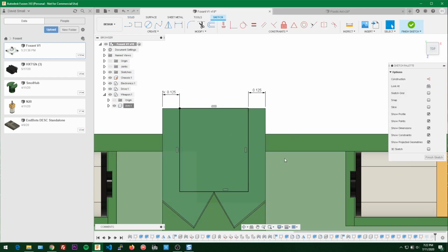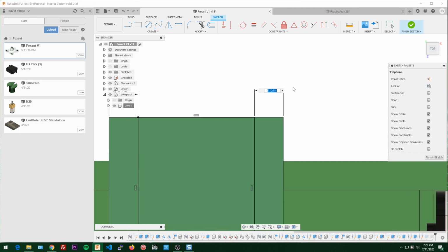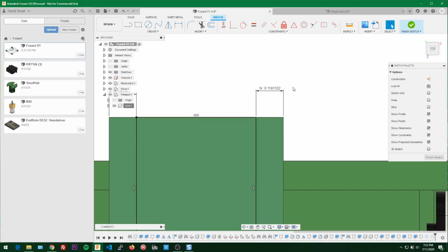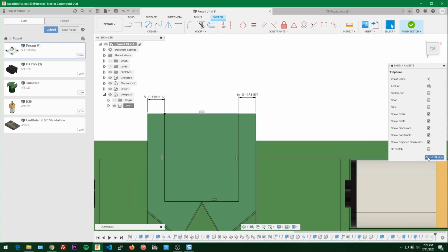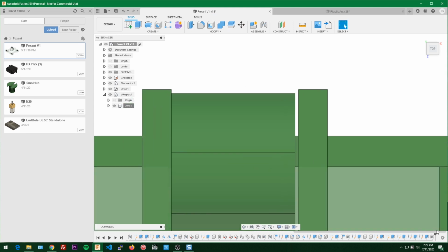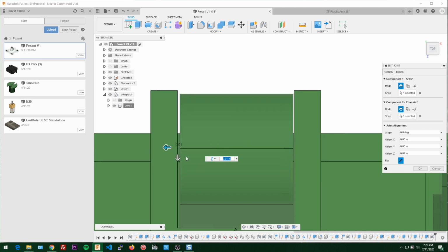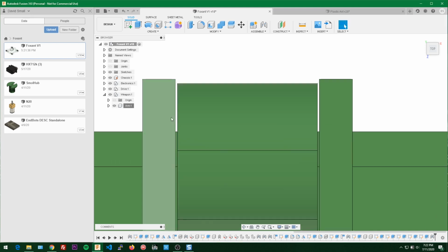So we're gonna have to carve out a little bit more so that it doesn't rub against the standoff too much. So let's change this to 1/8 of an inch minus slip fit divided by 2. That makes it a tiny bit bigger. So that will give us the space, but we need to adjust that gap. So let's go back into the joint and slide it over by slip fit divided by 2. And now we're nice and centered.